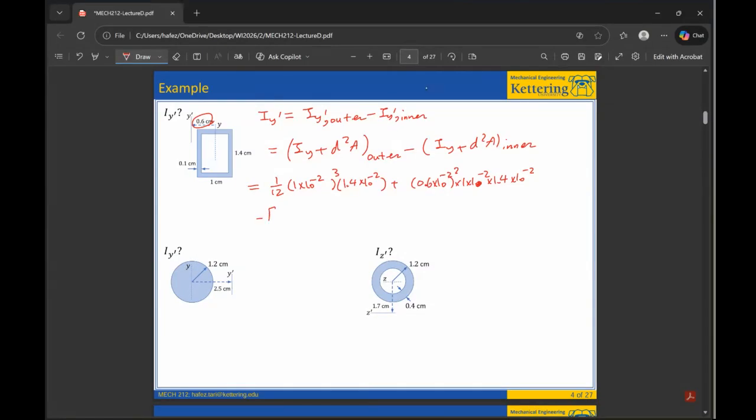All right, we repeat this, put all in brackets so that we're subtracting all of it, not just some of it. Now the focus is just on the inside. A new rectangle, new dimensions, but the same idea. So 1/12 base and height, offset squared, and these elements should go in here and here. So base and height, if I retain the same order that I picked in here and here, then this should be cubed. I can confirm that once I put the numbers also.